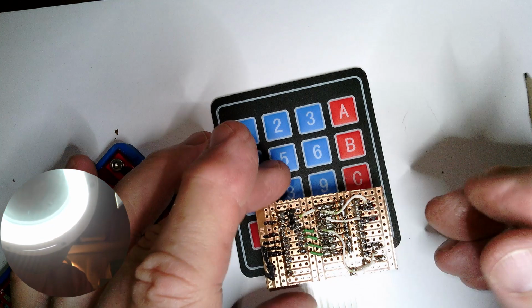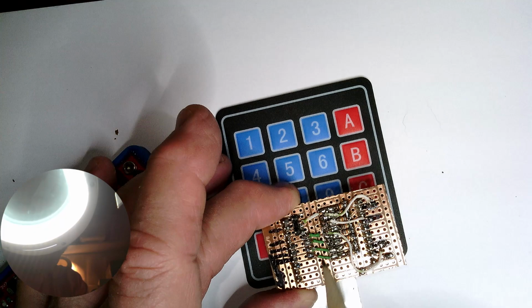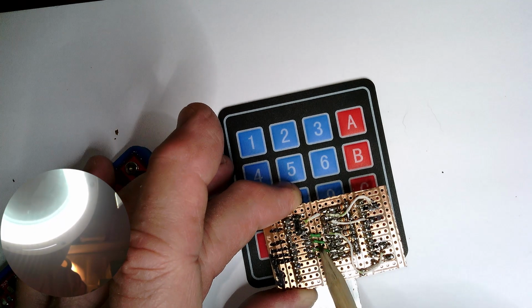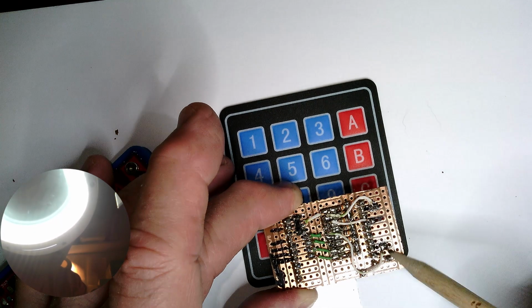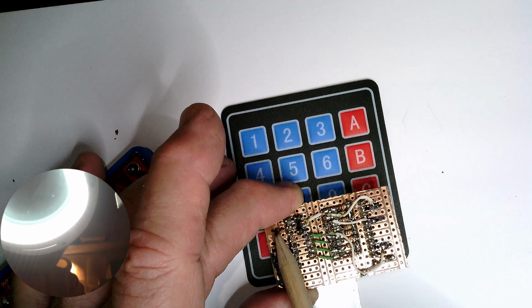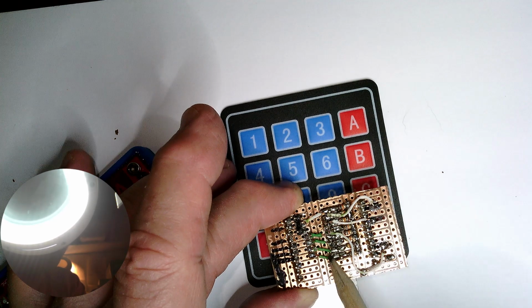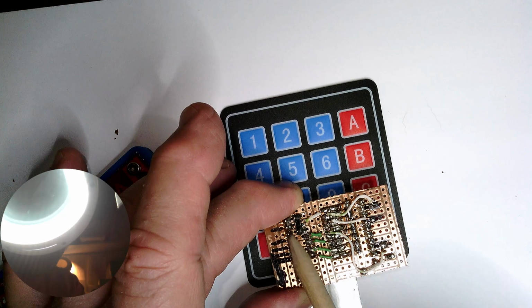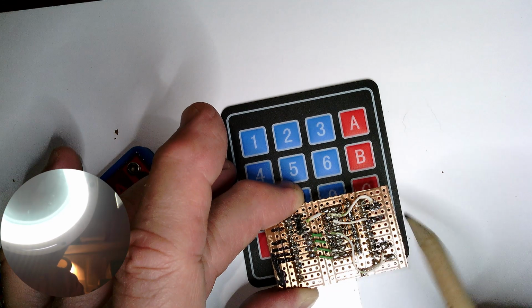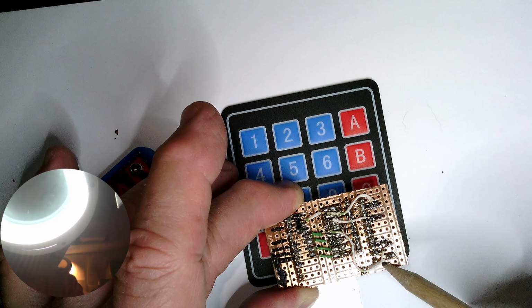Maybe. So you can see here, the green wires are the columns. The white wires are connected to the rows. So remember, the chip actually has 20 pins, and I'm going to talk about that in a minute. And I'm only using 8 of the pins. So the green wires go to the 8 pins I'm using here. And it turns out all these are on this one side. And then the white wires, one's here, and then one's here, and one's there. They're spread out a little bit more.